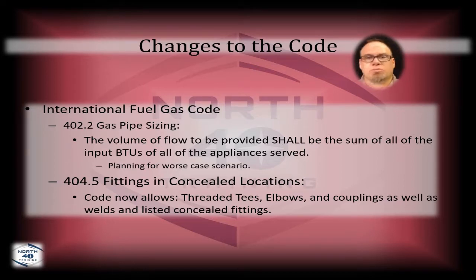Now, where do you run into problems on this? Sometimes you run into problems on the high efficiency water heaters, the tankless water heaters. Many of those, even their smallest sizes, are around 100,000 BTUs. And even though you might not use all 100,000 BTUs, you have to size your gas piping for that as a possibility. Oftentimes they're requiring a 1-inch line to come in dedicated just for that. 3/4 is fairly common as well.